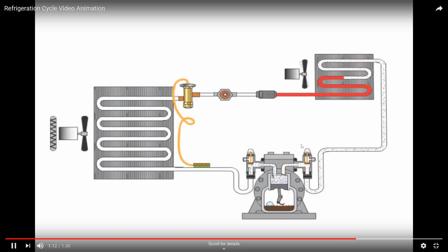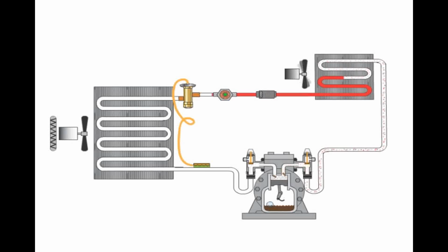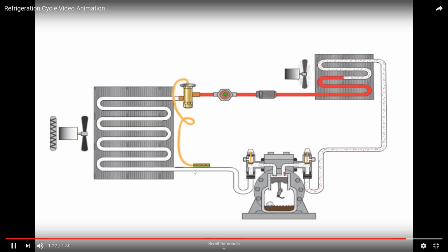And through this schematic, what do you need to know? Because this only shows how it works, but what would be the principle behind the important ones? In the evaporator and condenser, there is no temperature change because there is only phase change from liquid to vapor or vapor to liquid, ideally.